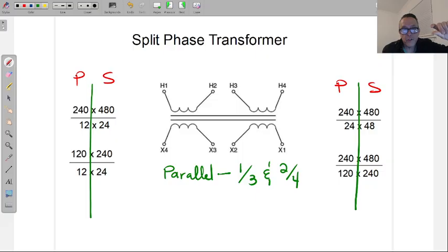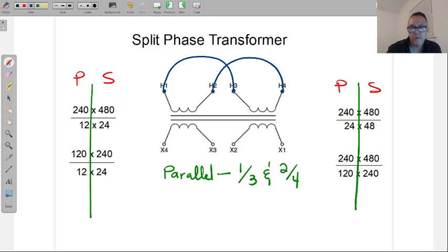Now, how this is done is with jumpers or with jumper wires. Either one is fine. On the terminal point, you would land one end of your wire, put a little jumper, and terminate it to 3, 1 to 3. And then same thing, little jumper. They sell these jumpers, and also we make them with our wires. For my online students, I'm going to set this up with video as well, and images. I don't think it's going to be video for this. We don't need it so much, but that's what we'd be doing. Stripping out, that's why you guys got wire stripping out, and jumping between the two.